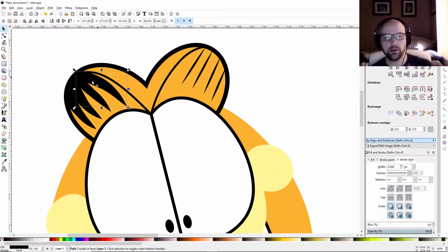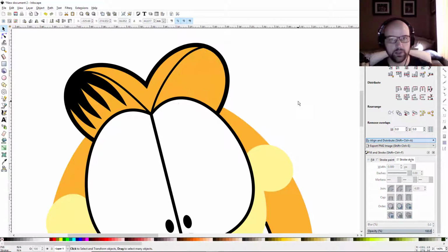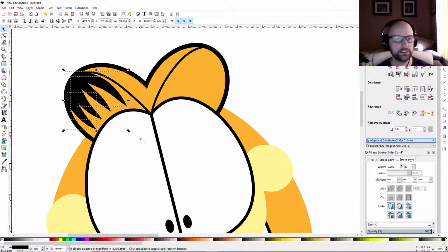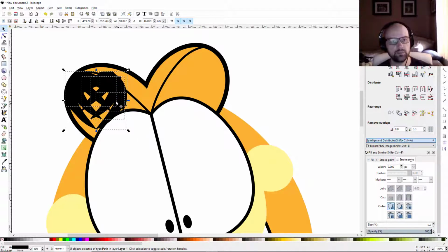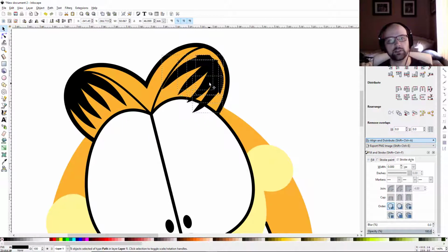Now we could go through this whole entire process again and recreate all that work over here on this ear, or we could just copy that and paste it over here, and I think that's what I want to do because this video is already running pretty long. So let me click and drag over all those guys, hold Control, hit D. Now I'm going to hit H to do a horizontal flip. I'm going to click and drag this over here,